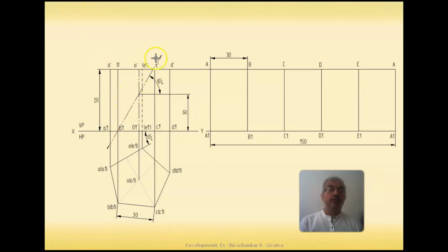So when we write the section plane, we have to make sure that this line is represented as a center line. And number 2, the two end dashes, the longer dashes at the ends of the line should be shown as thick lines. So that's the way we represent the section plane.